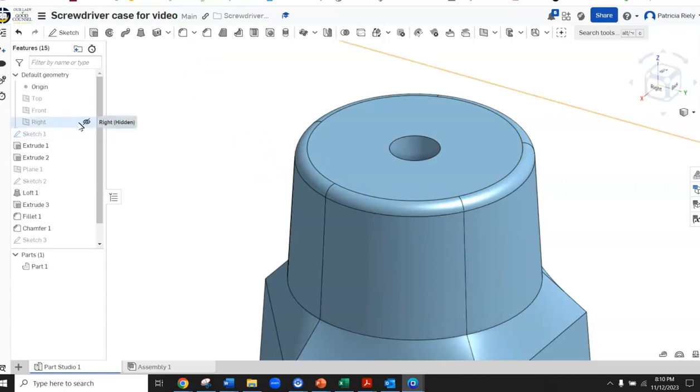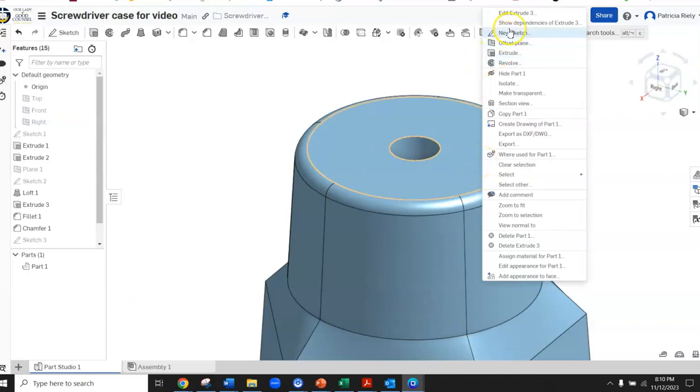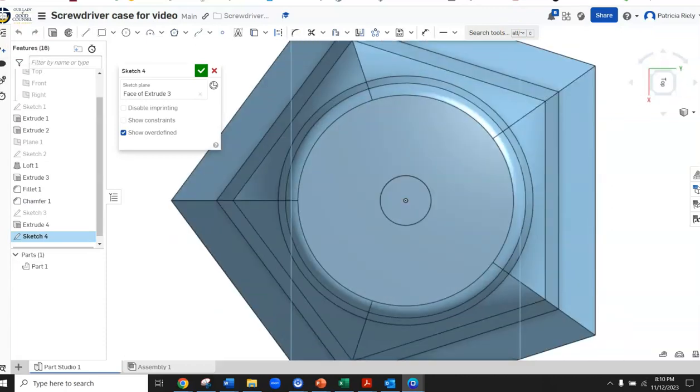Okay, next thing. Now create another sketch on top and duplicate the image below. The small circle needs to be aligned with the origin. Okay, so new sketch. Here comes a new sketch. Okay, so let me turn this so I can see what I'm doing. All right, so now I'm going to grab another hole, and I'm going to come here first, and I'm going to go vertically up. Okay, so see how I'm aligning it? That little dotted line shows up. So I'm going to put my cross right on top of that little dotted line,